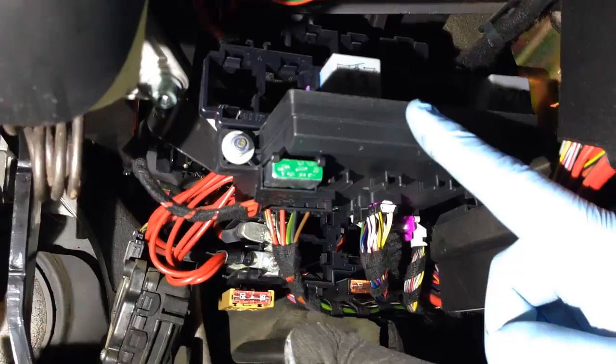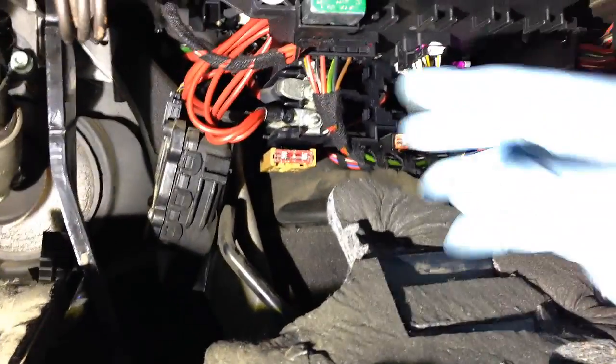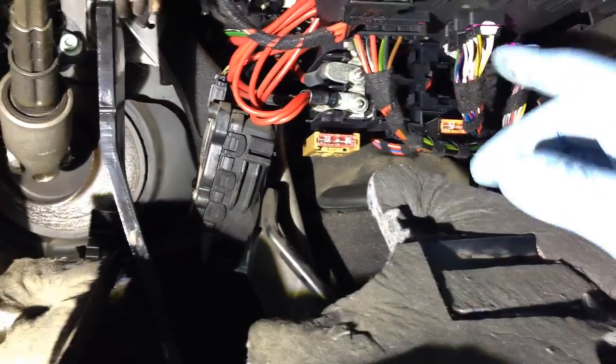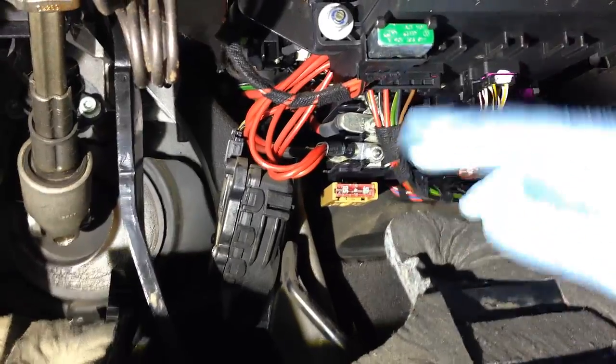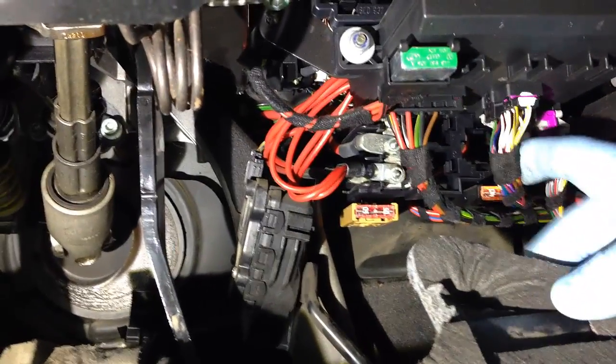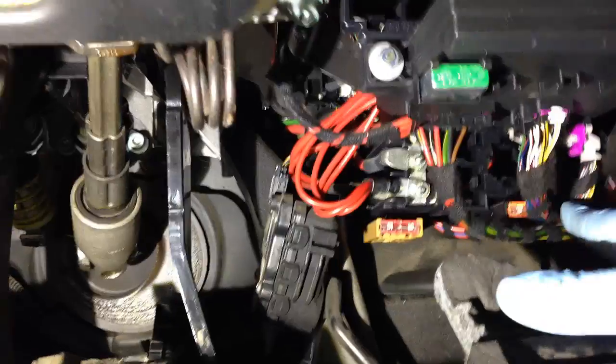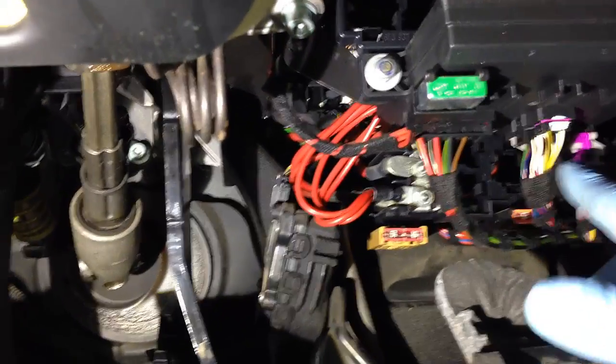Okay, so we've got some covers off. I'm just going to lift the camera in here and see if we can see what's going on. Here we have the onboard power supply control unit as shown on the diagram. I've just taken this cover off, and what we can see here are wiring connectors. There were 3 shown on the diagram, a 10 pin, I think a 23 pin, and a 32 pin. So we've only got 3 connectors on there.